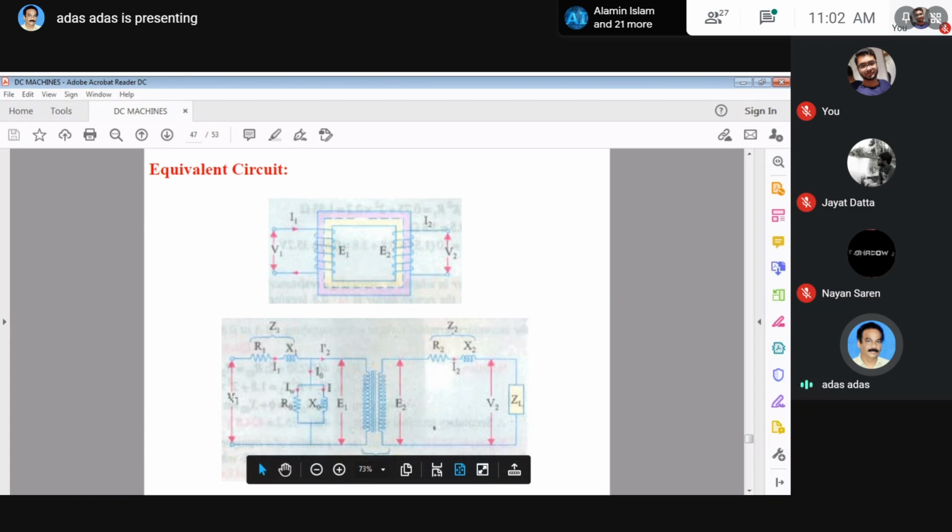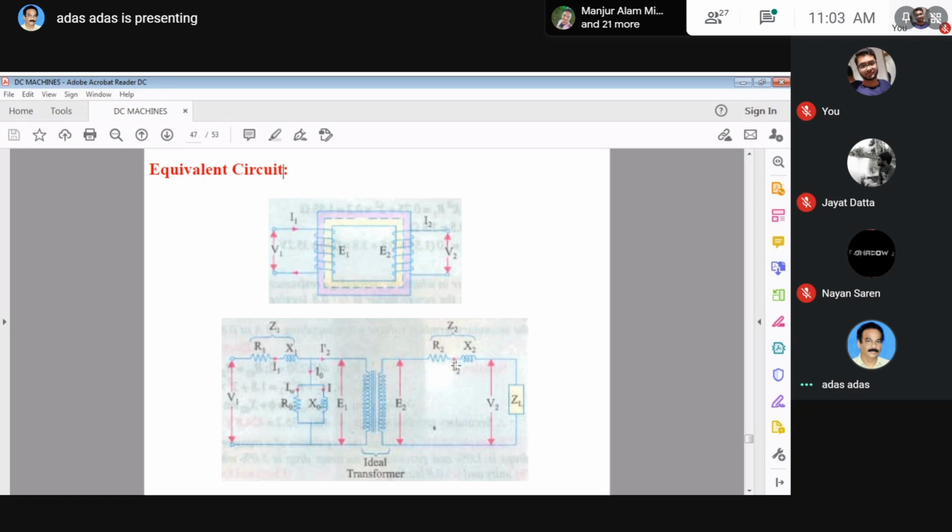Now, apply voltage V1. If you apply voltage V1, then current I1 will flow. Current I1 has two components, one is I0 and another is I2 dash. What is the purpose of I0? It generates the magnetizing flux phi and supplies some copper loss. It has two components, one is I omega and another is I mu. I mu passes through X0 and I omega passes through R0. Another portion is I2 dash, which gives you the load current, which is nothing but the reflection of the current I2. I think it is clear.